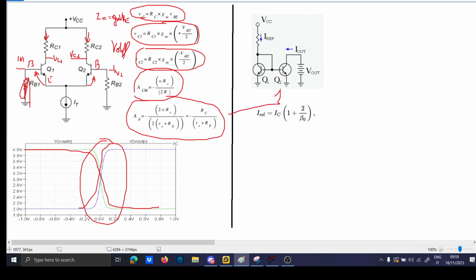This guy instead is a current mirror, as you may know from a lot of courses. Just a little reminder that the reference voltage is given by this formula here. But in practice, you set the reference voltage with this resistor and with this voltage here, and the same voltage will apply in the other branch. So the basic idea of a current mirror is to use a current to voltage converter combined with a voltage to current converter. This is a voltage to current, and this is current to voltage. And so you have a current mirror.